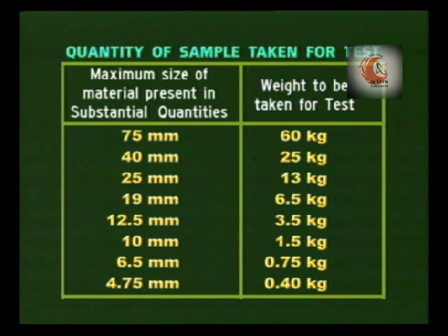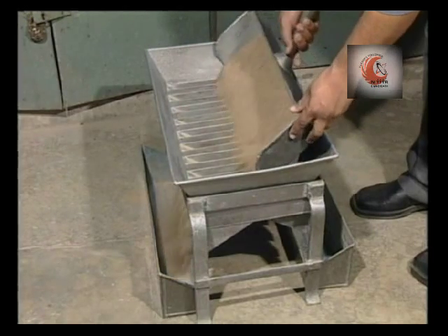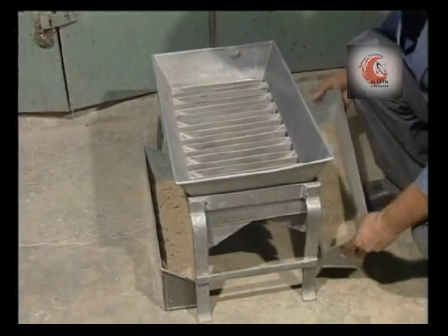Similarly, we can take the weight of the sample as per this table. Take a representative sample of soil by using a riffler.